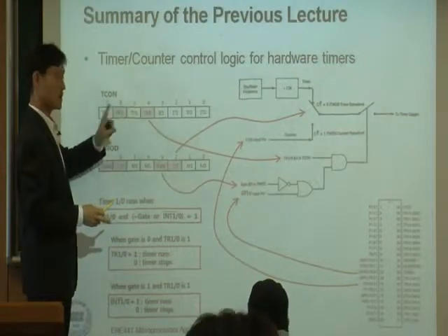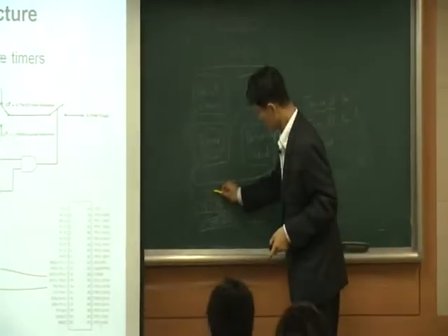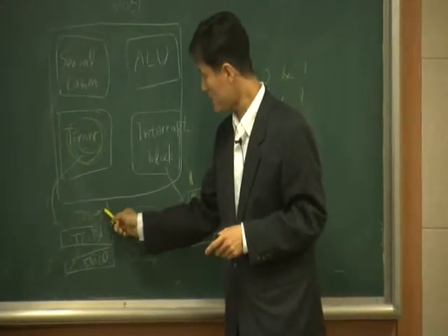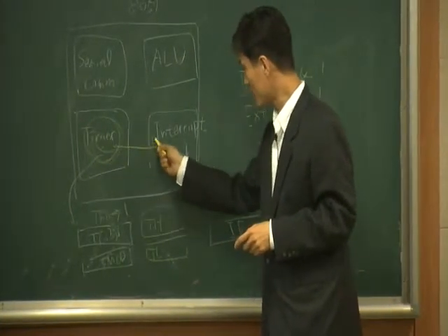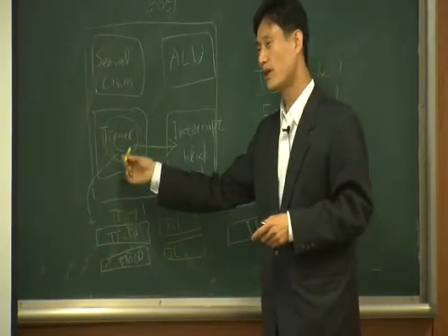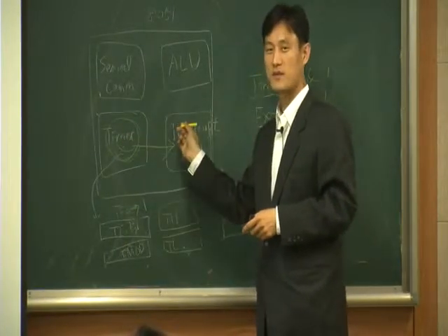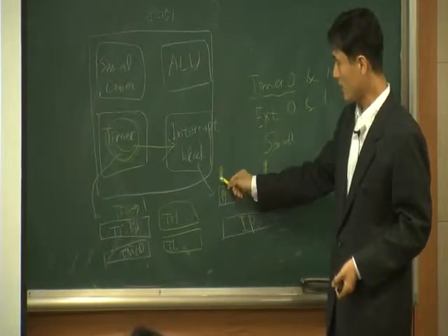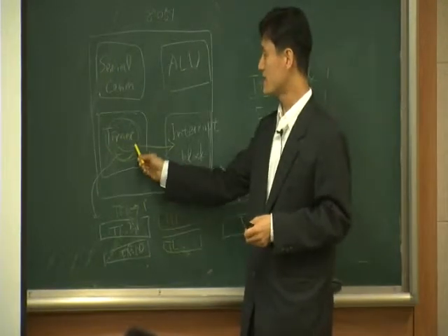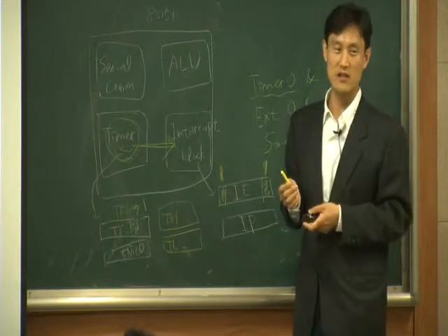And once this bit becomes 1, when the TF0 bit suddenly becomes 1, that basically means the timer is now sending an interrupt to the interrupt block. Okay, now the timer hardware will set TF0 equal to 1, meaning that it's getting an interrupt. So finally, now we enable the interrupt by setting these 2 bits, and we also have the interrupt event. So therefore, now we actually get an interrupt to the software.